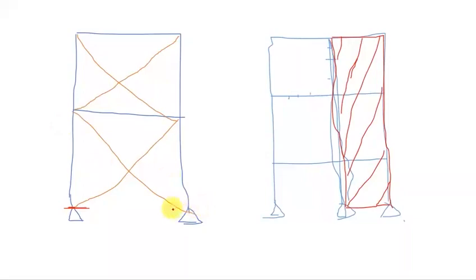That means, maybe an example, you have a connection here. Say it is a moment connection. This means this connection will transfer moments. What do I mean by that? This connection resists bending. So if you apply a lateral load at this point, then this member, at this point, will resist that bending. But if it is a pinned connection, then it will not resist bending.